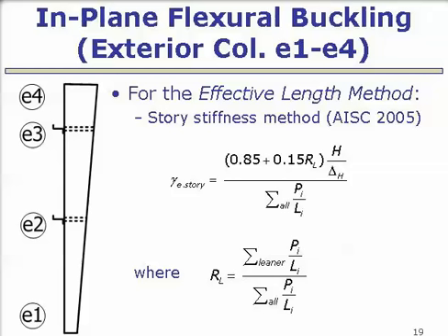So the buckling load I can get by, if I have wind load or some other horizontal load on the system, or if I just put a notional load, an arbitrary lateral load H on the system, I do a first order analysis, I get a delta H. That's the sway of the system under that load.